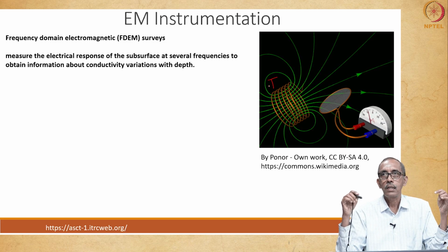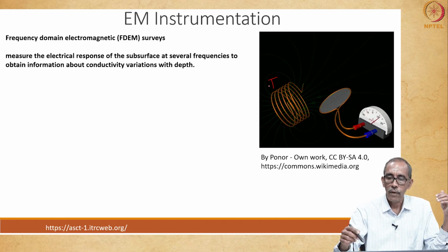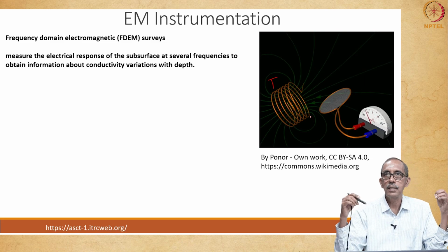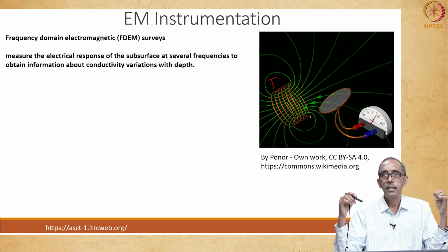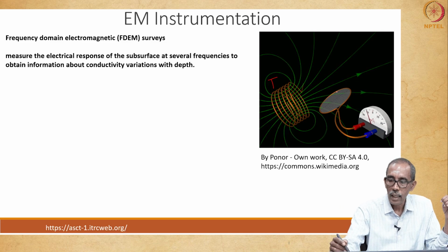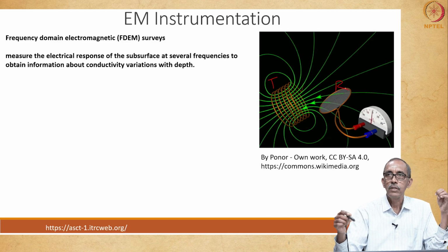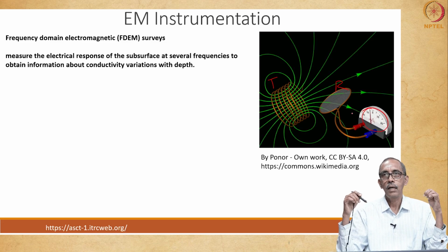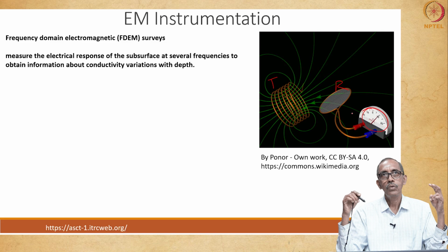Through the transmitter coil, we apply some current, which in turn develops some eddy currents within the surface, as indicated by this secondary field indicated by green color, that is sensed by a receiver coil, right. So, receiver coil measures the current that got developed below the surface, but measurement can be done in two ways.